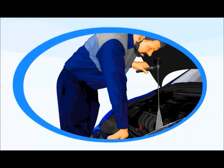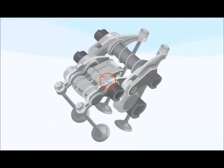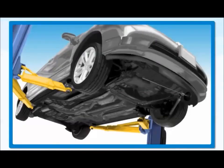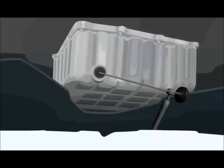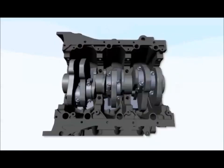Scopes also allow technicians to perform other checks inside the engine. Openings in the valve cover allow you to view the valve train for mechanical or sludge problems. Under the car, inserting the borescope through the oil pan drain plug opening allows a view of the crank and oil pump. This check may identify crankshaft or connecting rod faults or excessive sludge buildup.